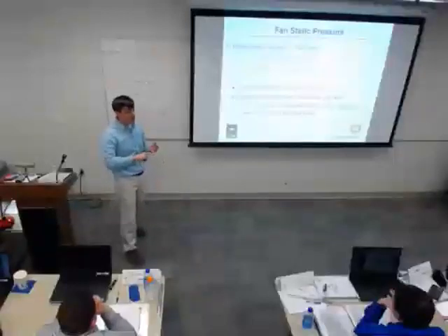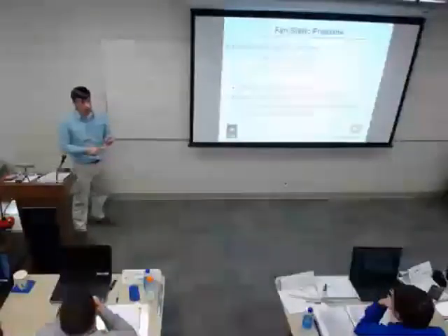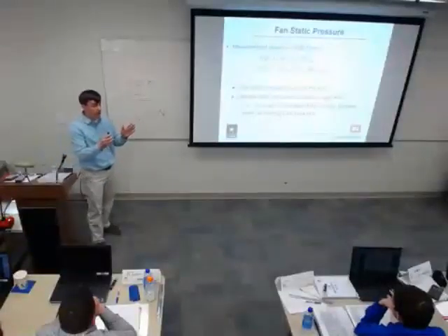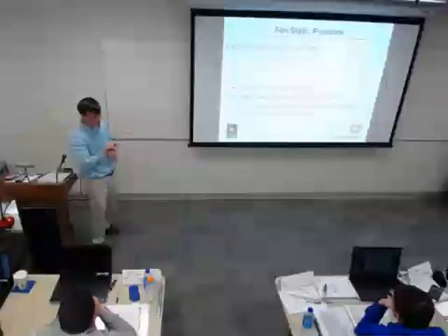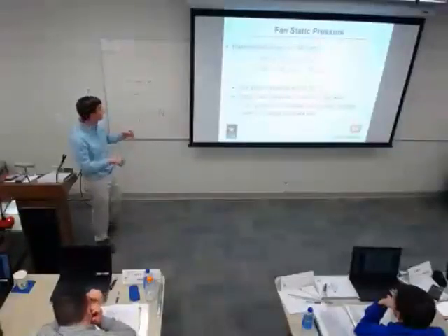So you definitely verify it in the submittal phase. You want to make sure that's going to tell you if you got a big enough fan. You're going to check that on the fan curve. They're going to give you a fan curve as a part of their submittal and show you what my operating point is, and tell you what motor size they're giving you with it. Those are all things you check in the submittal phase. And then yes.